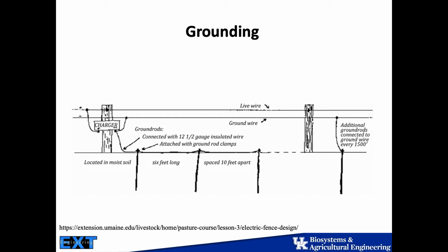And so every time you move a solar box, you have to have a good grounding system wherever you move it to. So if you're like me and you have a farm that doesn't have electricity and you don't have good permanent fence that you can run electricity inside of, you have to move that solar box, and every time you move that box, you have to put 3 ground rods in the ground, and you curse yourself every time for not having a single point that is going to control your electricity for the whole farm.